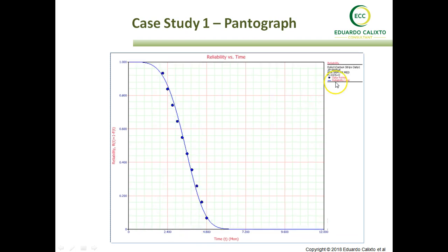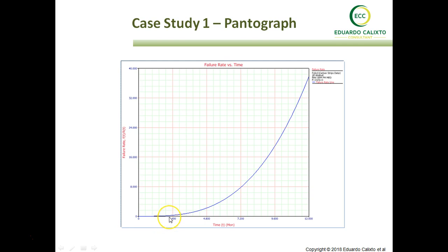Okay, so as well as you plot the PDF, automatically we can also have the plot of the reliability function. So we can see the reliability in 2 months is very high, and after 2 months it starts to decrease. So 2 months would be a good time to make some intervention. So here we can confirm that when we plot the PDF failure rates in software, we are also able to anticipate the failures after the increasing failure rates.